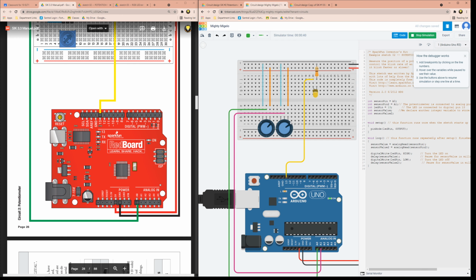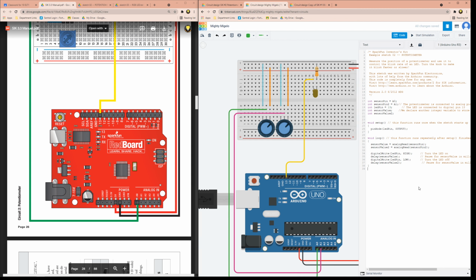We could, instead of making this sensor value just choose how long it's on and off, also make this sensor value be a multiplier, so we can actually have it as a ratio. But for now, these are just two values that are there. Let's say right now full on is only 1 second. That might not be enough for us, so let's stop. Let's change our sensor value, analog read pin 2, and times that by 2.